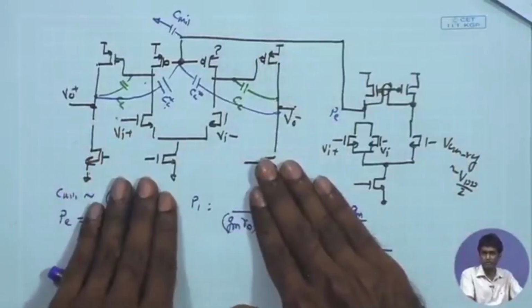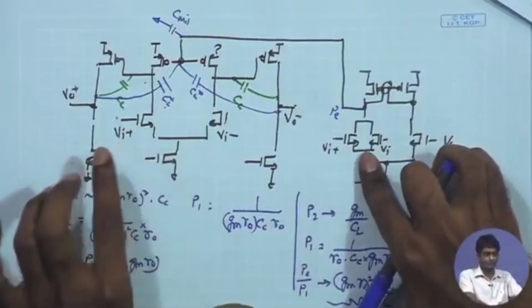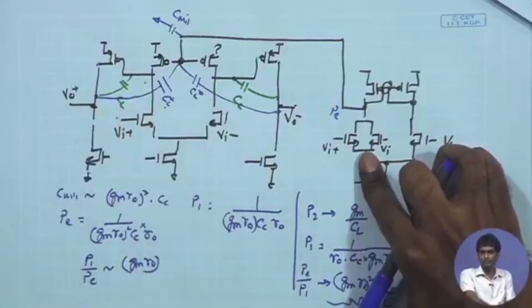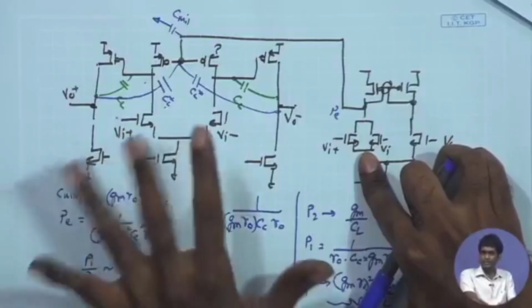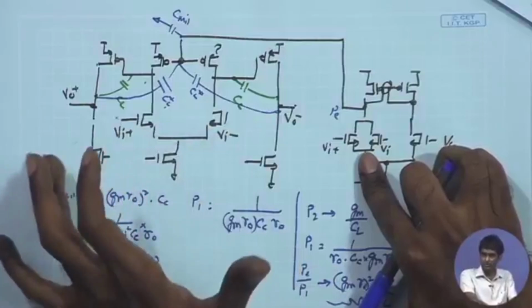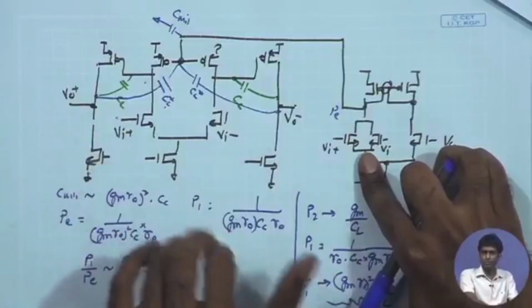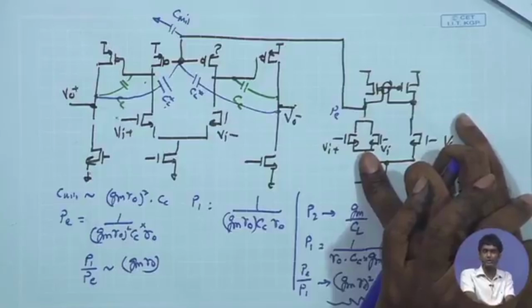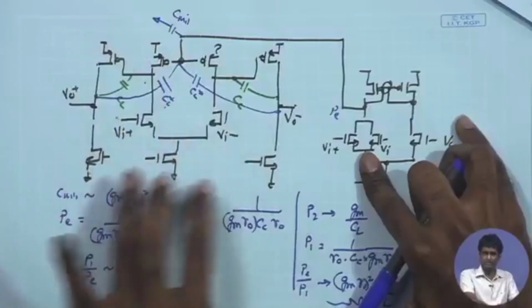So, so far we have not given you a transistor level design example, where you can at least estimate the values of the CC and the transistor sizes W/L, etc., given higher level specs. So, here I have just shown you so far the steps for analysis, that okay, for noise analysis this is the step, this is the sizing direction through which you can reduce the noise, these are the ways you can compensate the differential loop and common mode loop, but we need to take another example where, given these specs at higher level that we have arrived for our front end amplifier, how to arrive at these values of CC, CC star, or the sizes of these transistors.